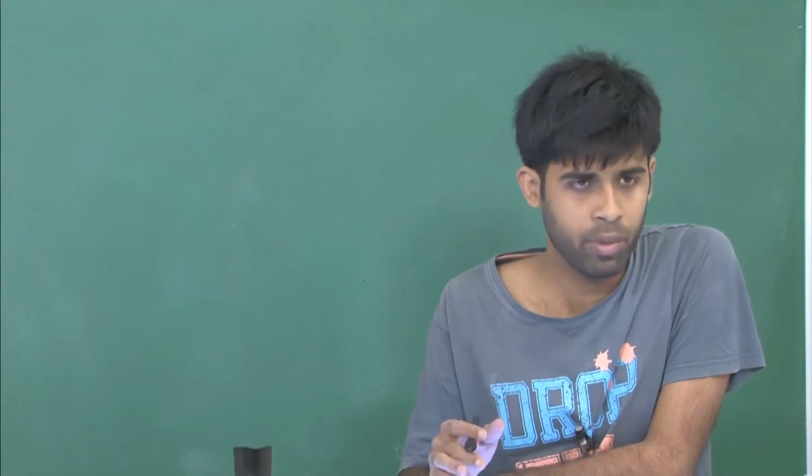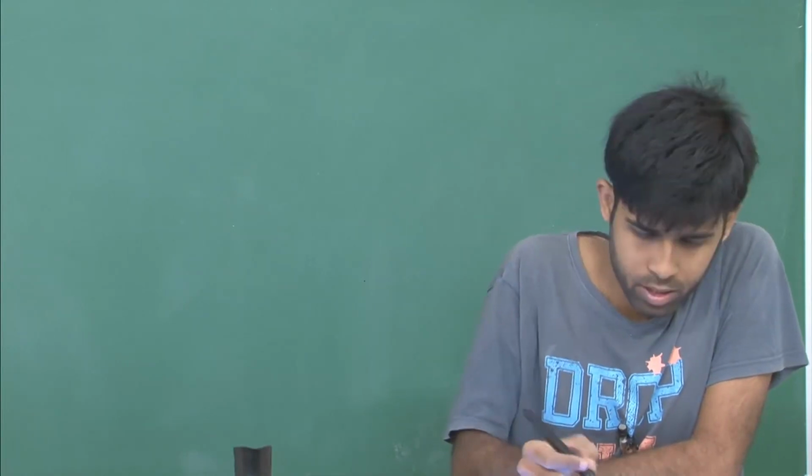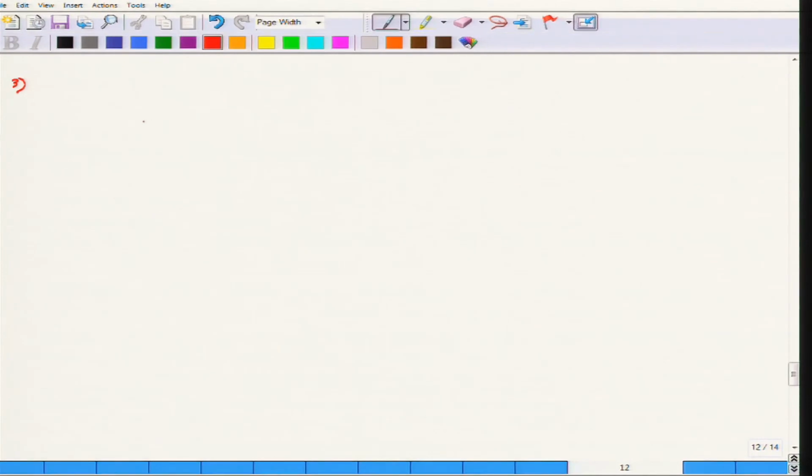Also, above shear strength means above testing of footing for whether the soil can hold its strength or not. The next important factor that you have to consider is whether the structure would allow a settlement within permissible limit or not. That is why an extensive soil investigation is always required, by constructing different boreholes, in order to know the exact profile of the soil. A soil profile is not uniform everywhere as you see in problems; rather, it is very different.